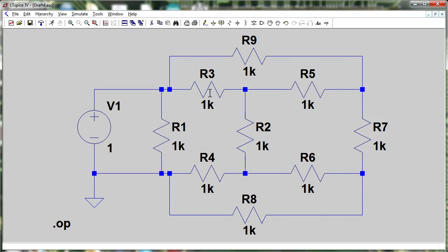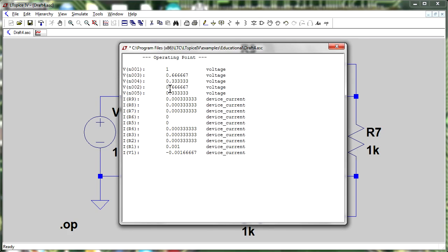You can muck around with this and get those values, or you can just leave it as it is. But understand that a component like a resistor has a particular direction. It's not just a random pin allocation. It treats the current flowing through in a certain direction. So we can run that and we should now get all positive currents flowing through our resistors. Too easy. We've done our first simulation, DC operating point analysis.